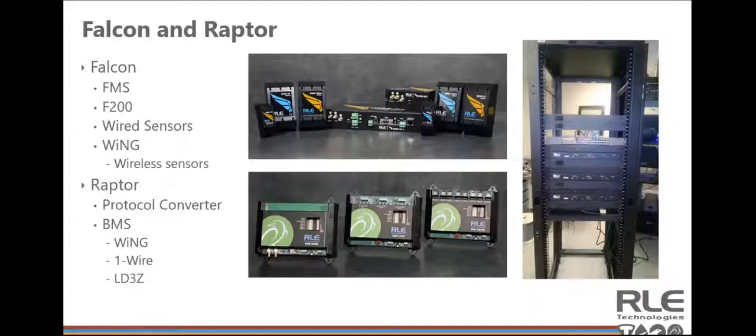It's a wireless sensor option. It allows you to basically quickly deploy sensors to an environment without going through a whole bunch of cabling, install, and setup for that. The newer line products are like wireless airflow, velocity sensors, differential air pressure, leak detection, so on and so forth.